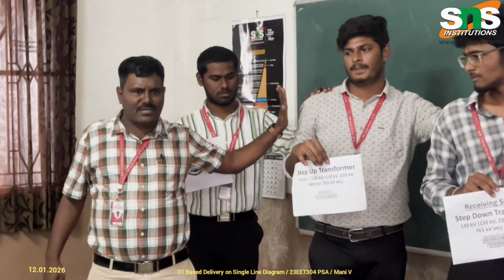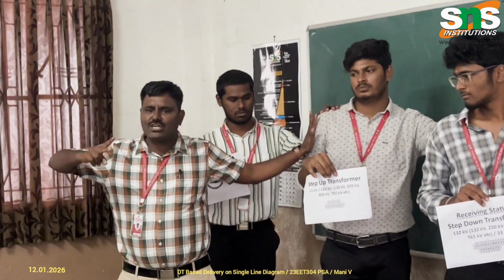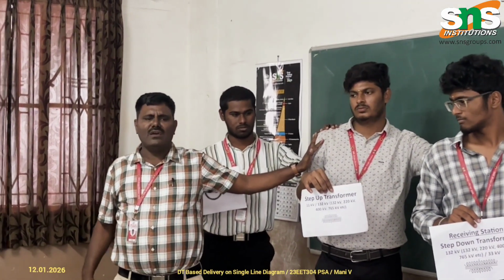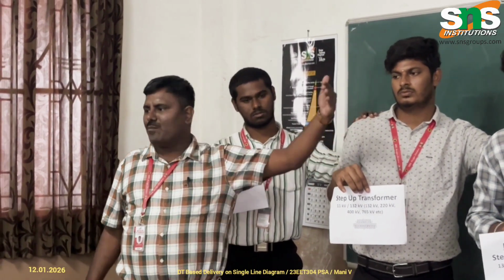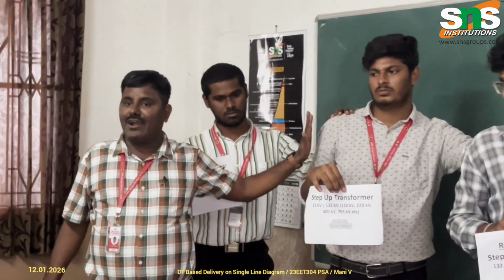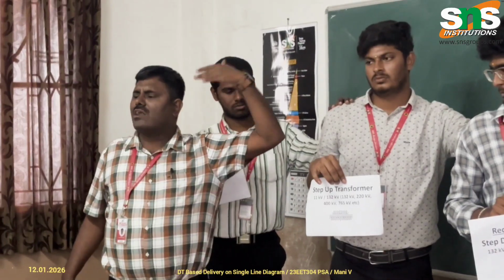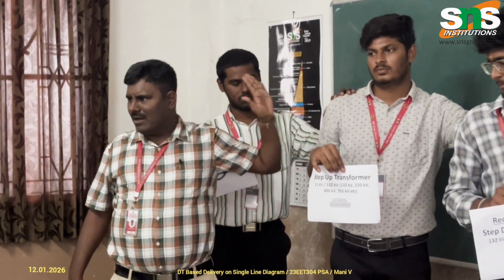This step-up transformer always converts the low voltage into extra high voltage or ultra high voltage, based on the distance over which we have to transmit the electrical energy. Based on the distance, we choose the voltage level. So the 11 kV can be converted into 132, 220, 440, 765 or 1100 kV, etc. This is the only step-up transformer in the power system.